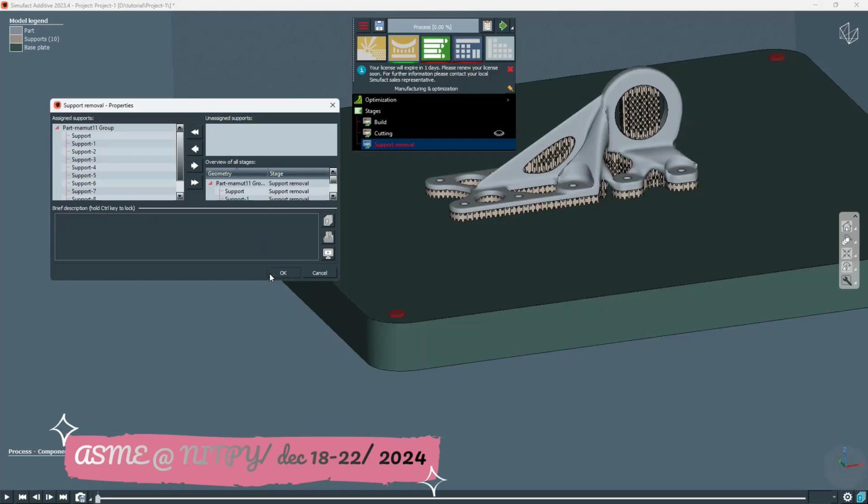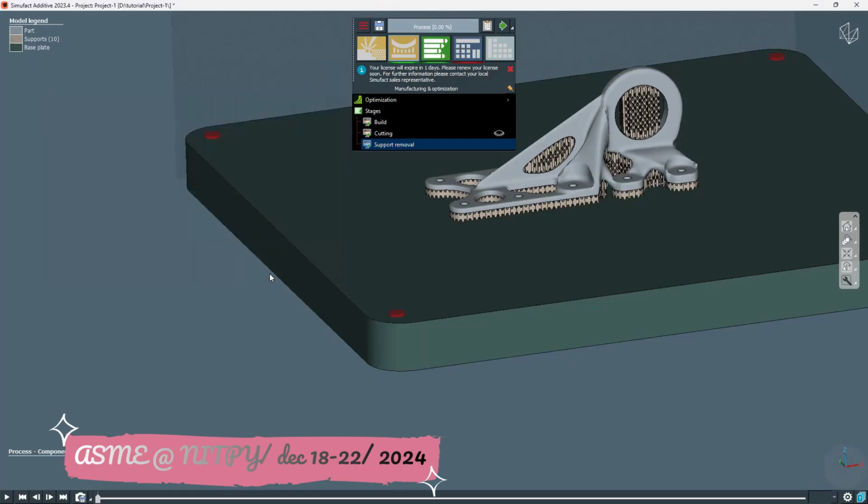So now you can see if you give okay for that, all the stages will become white in color. Nothing will be written in red color, right? Once you give okay. And also you can observe one more thing, on the top, the icons will be green in color, like this. One green line will be there. If you have not defined anything inside that window, you can see that there will be a red line, which shows that it is incomplete. Something needs to be defined or something we have missed out. It denotes that kind of thing.